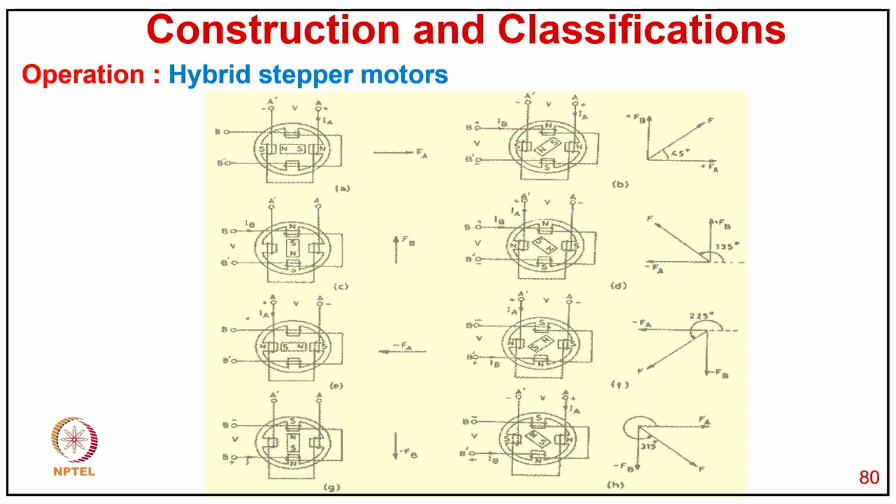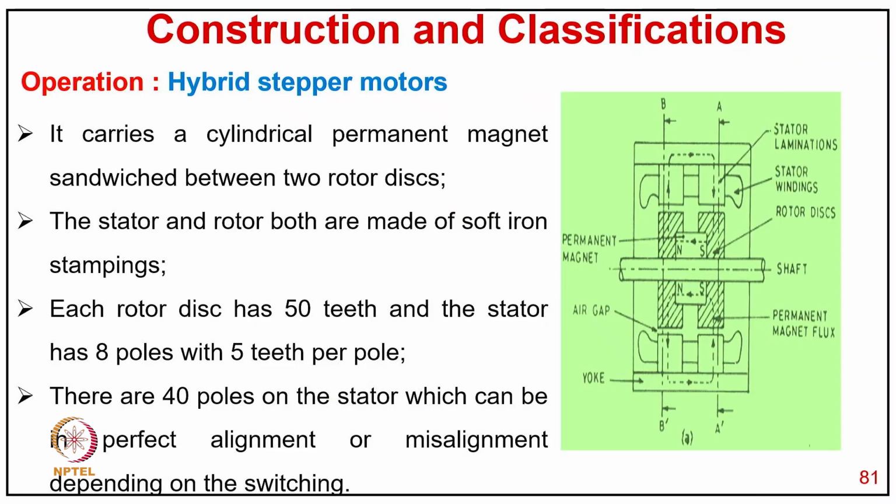So all these, really you can look into how the excitation and the field position is there. Typically here you can see how different parts are clearly visible and how the flux path is there. You can see in the magnet it is parallel to the shaft, we call it axial flux movement, but in the rotor teeth as well as in the stator teeth we have flux moving radially, and on the stator core also it typically moves axially.